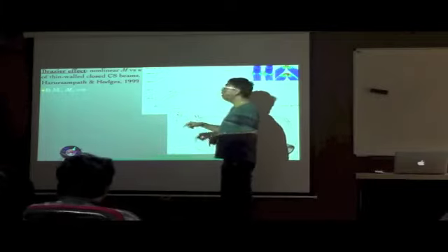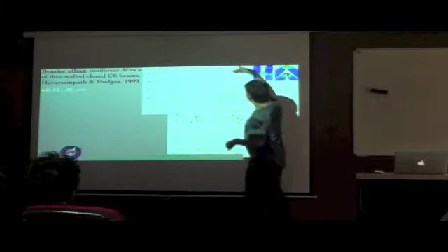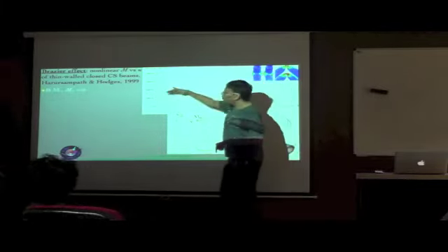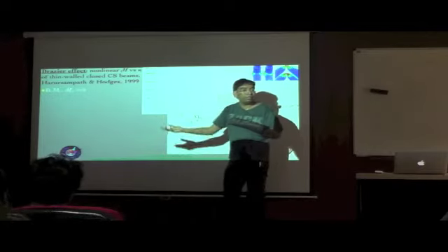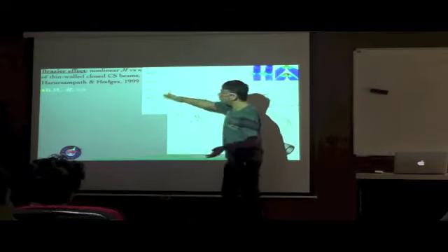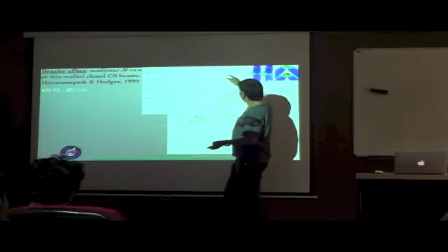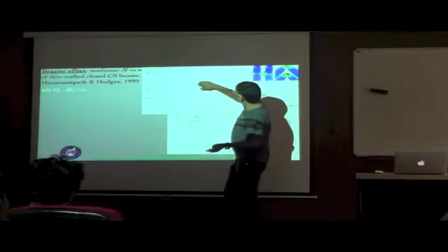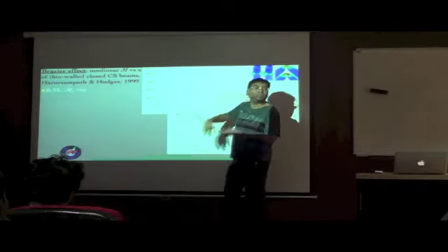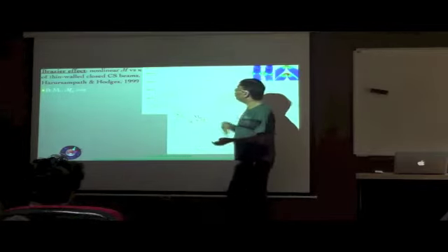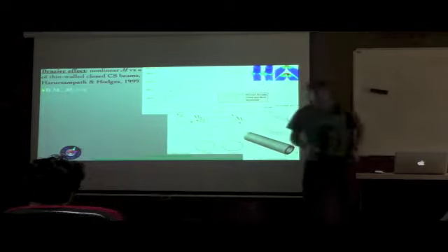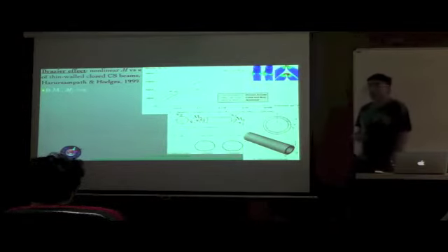So in that sense, not only for the prediction of the limit moment instability itself, which in some cases could be just a theoretical value if the other failure has happened prior to that, but to predict even that other failure, the nonlinear behavior has to be taken into account appropriately in order to predict its value more accurately.